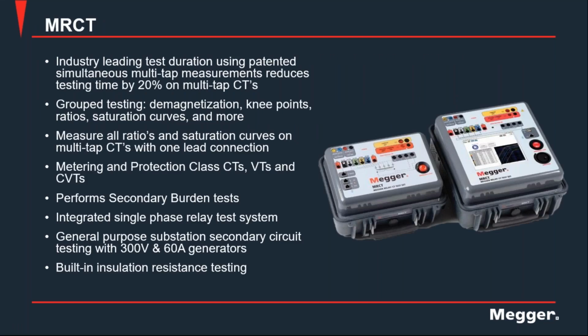Of course, we have instruments that can do all of these tests. We have the MRCT, which is an instrument that has a patented method of simultaneous testing, the concurrent method. And well, you reduce the time of testing drastically. And it's also an instrument that can perform tests on all types of instrument transformers, CTs, VTs, and CVTs as well. And it has metering accuracy, with also the possibility to test relays with this instrument.